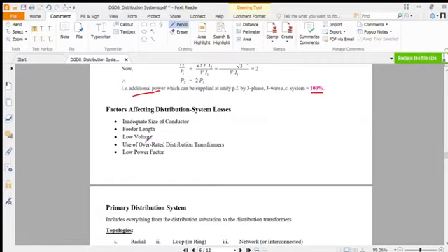And the voltage: for low voltage the current will be higher, and the I squared R loss is higher, whereas the transmission line voltage would be higher. The distribution transformer must be according to specification, and a low power factor obviously needs larger kVA equipment as well as a thicker conductor, and it definitely increases the loss as well as the cost.